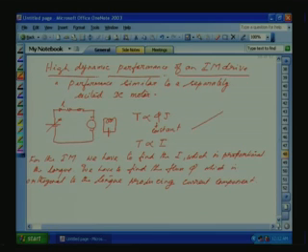Vector sum means IS should be a vector sum of two currents in orthogonal directions. Suppose this is proportional to torque and this is proportional to phi. Then changing the torque producing component will not affect the flux, because they are orthogonal, and only then can we say the flux is kept constant. So we have to find, from the induction machine model, the flux which is orthogonal to the torque producing component. So let us study the dynamic equivalent circuit model.